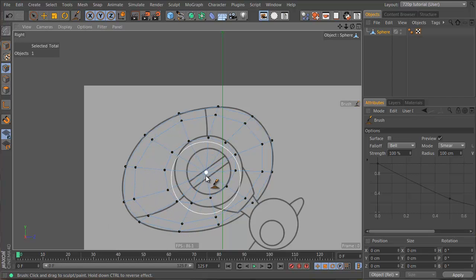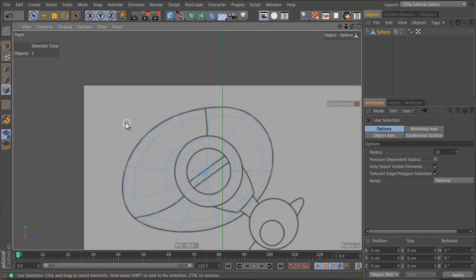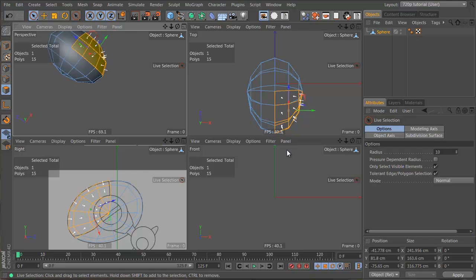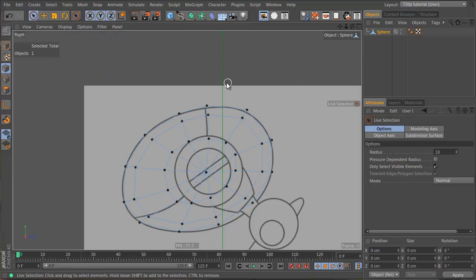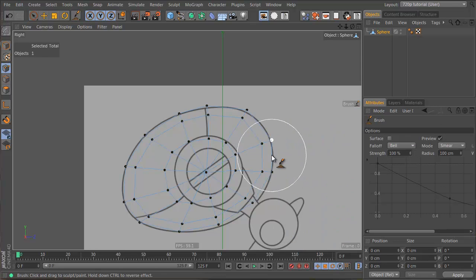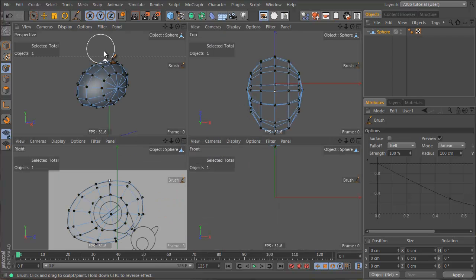Because this is probably going to be the line where our curve is, where our screen is going to be. So let's just shift this guy around a bit, because we're going to cut these polygons here. We're going to extrude them to get our front screen. So we're shifting them around in point mode with the brush tool, just to make it meet up with our reference. And we want the center to be probably around here. It's not super important, but sometimes down the line this comes in handy to line things up when you're starting out. Okay, I think that looks about right.